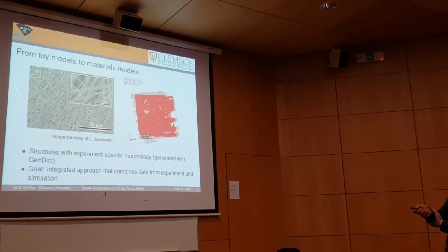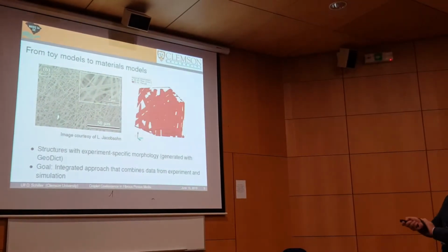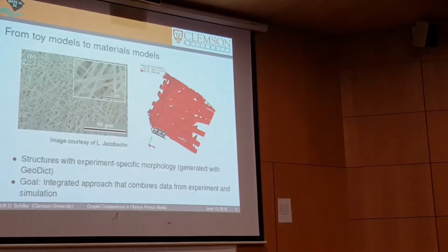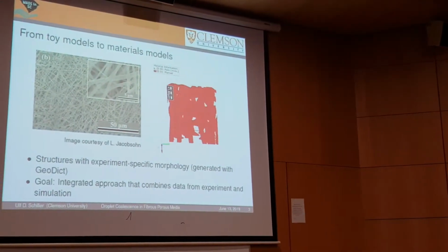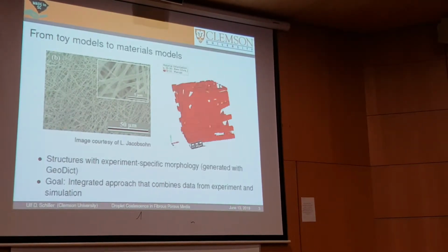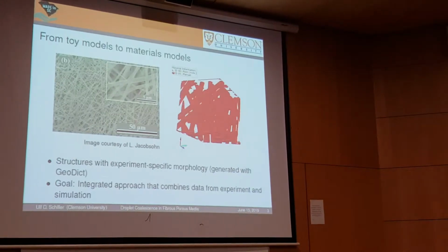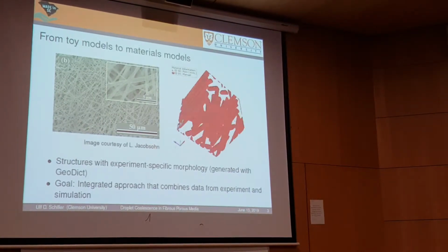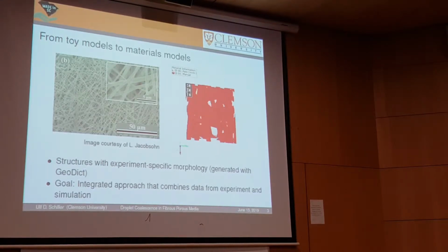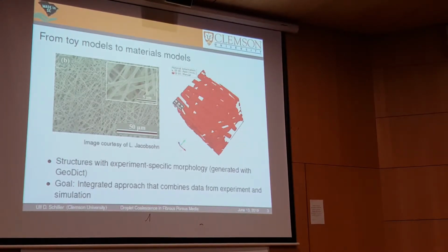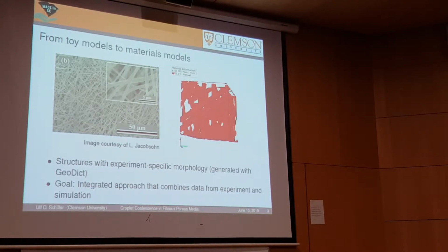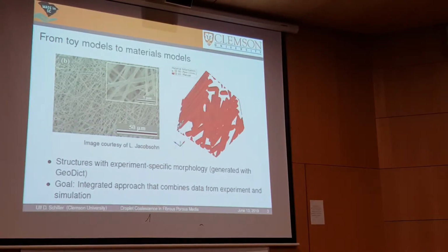These materials actually look like this, right? So this is a non-woven filter, if you want. This is produced by electrospinning of fibers. Fibers are shot out from a nozzle and then just deposited onto the surface, and they give these random structures, so that's relatively easy and cheap to produce. You can see these structures are on scales of microns, but eventually the material is something like you all know. It looks like this on this scale, so to say. This is a non-woven fabric in a sense.